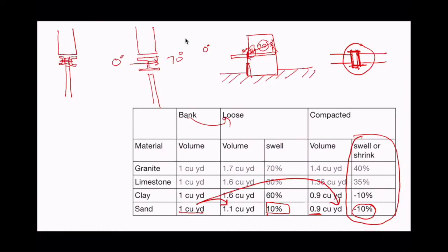And we can bolt it together, and now it looks the same from the inside and the outside, but we provided a thermal break. So this is a thermal bridge, and this is a thermal break. And thermal breaks are meaningful. Thermal bridges are meaningful. In cold climates especially, they meaningfully reduce the insulative value of the skin of the building.